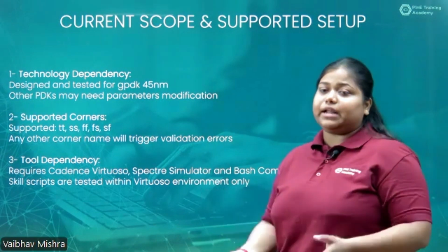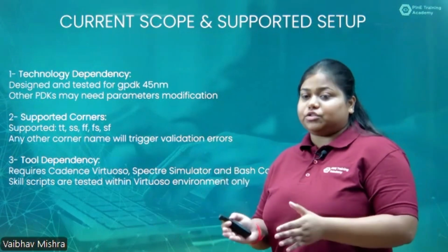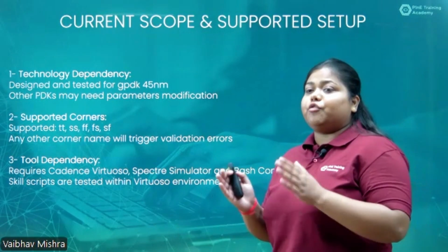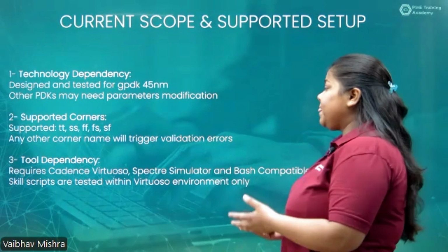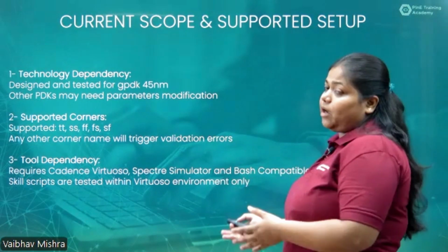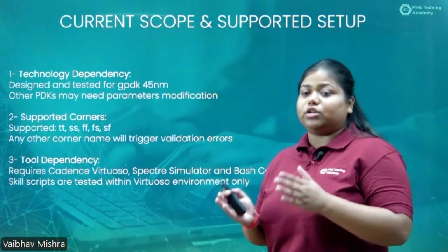So what is the tool dependency? The path on which the user is currently working or executing a project must contain the Cadence Virtuoso, Spectre simulator, and the bash compatible shell at that particular path on the terminal.